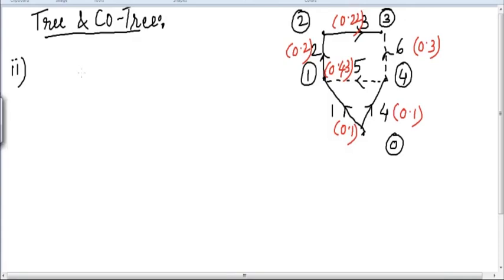In the second bit, what they have asked is the basic loop incidence matrix, which is denoted by C. For C you all know the requirement: to close the loops one by one, and whatever path is formed is to be written in the matrix. We will draw the graph, tree and co-tree once again, because the earlier drawing is the answer of the first part, so we will not do anything in that. Instead, we will make another tree and make all our loops in that tree.